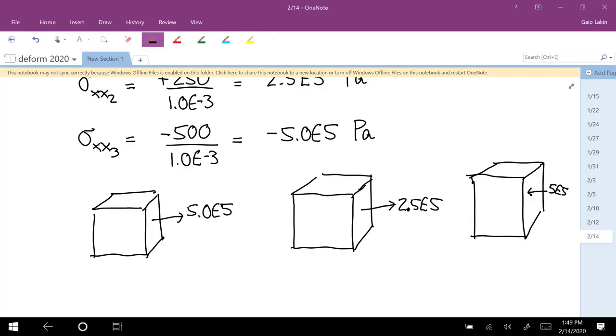All right. One thing that's sort of interesting, now those represent stress tensors, so you could go to the stress tensor and then you could calculate principal stresses and whatever. Well, what's the principal stress tensor for, let's say, this one? Do it in your head. Yeah, right, it's already principal because the only stress is normal. And so what's the maximum shear stress? Yep, 2.5 times 10 to the fifth.